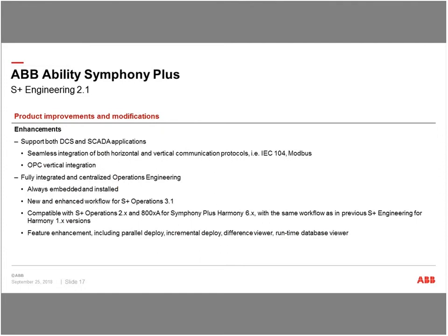And then some other enhancements: we support DCS and SCADA application. SCADA is basically not using an ABB controller, but just using Symphony Plus operation with some standard protocol like 104, DNP, Modbus to retrieve the data from another device or controller. But for install-base customers, there's also a benefit.